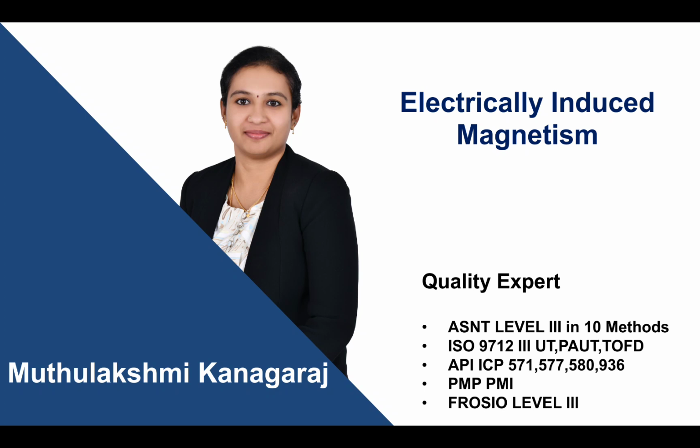In our previous session, we extensively discussed magnetic flux and flux leakage, understanding how these invisible lines of force become visible indications when disrupted by flaws. Now we are going to dive into electrically induced magnetism, which is the primary method used to create magnetic fields in the test object during magnetic particle testing. This topic builds directly on our understanding of magnetic flux and how it behaves around discontinuities.